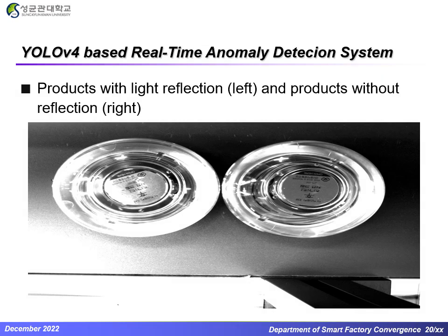As I explained in section 3, since the inspection material of the product is a sticker, reflection occurs when light shines directly on the product, so the image is not accurately acquired. Therefore, by correcting the angle of incidence of the light illuminating the product, it is induced to be illuminated with indirect light. In addition, when the camera shoots a product vertically, light reflection may also occur. So the angle of the camera is adjusted so that light reflection does not occur. The figure is a picture prepared to understand the above explanation.